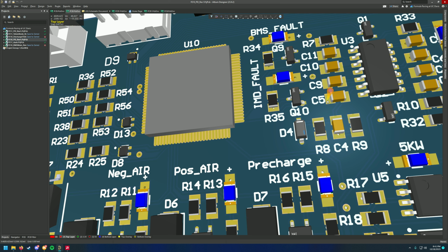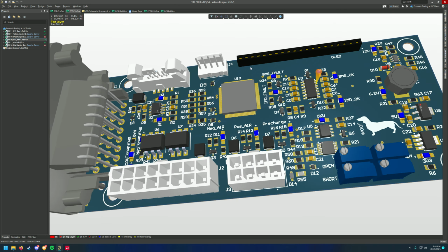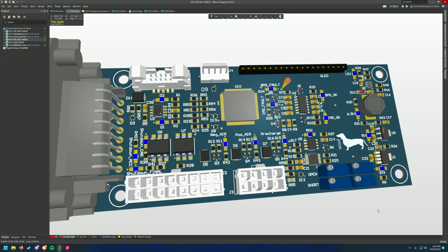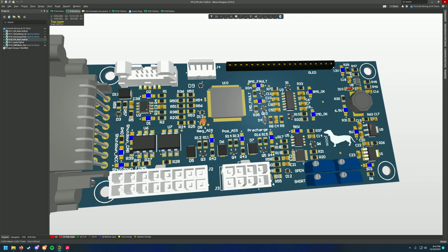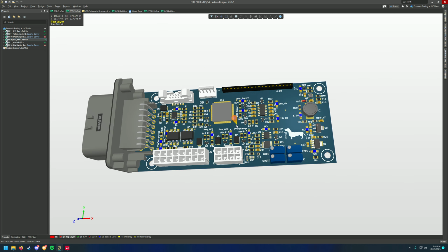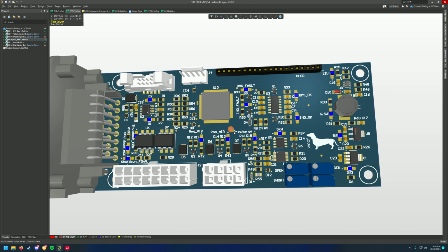You can basically just think of it as solder that hasn't been melted yet. Then you put the components on top of the solder paste and stick the whole thing in the oven and solder all the components at once. It's a lot harder to do that with through-hole stuff, so that's why you see a lot more surface mount stuff these days.